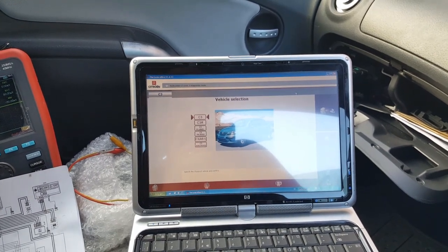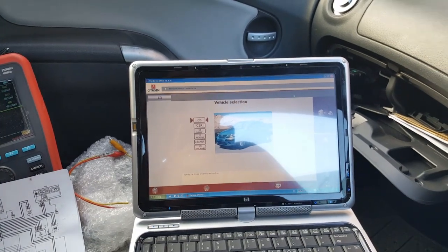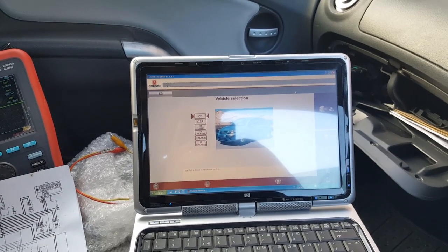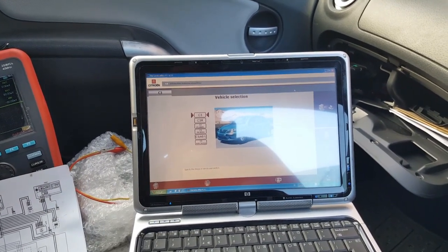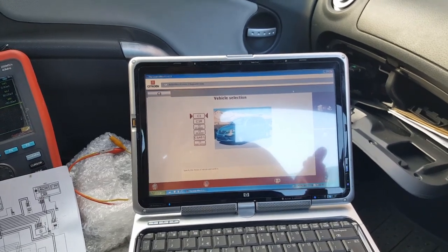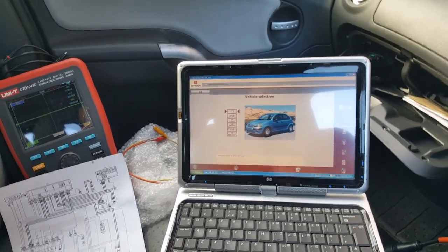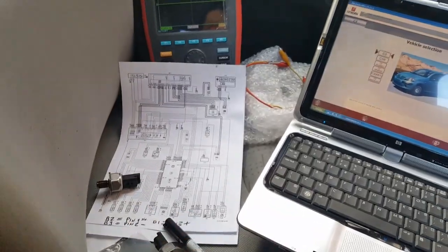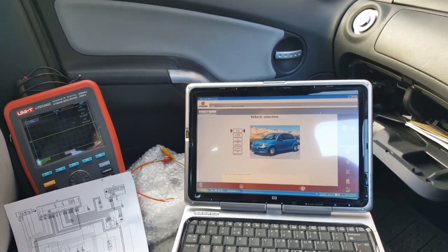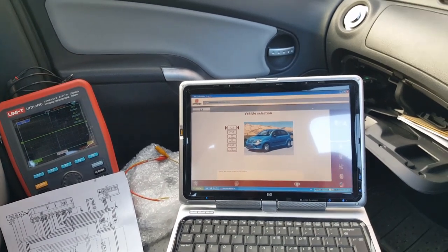When I checked the freeze frame, which tells me the status of the engine at the time of the fault, it showed 1700-something bars, which is obviously full pressure. When I measured the sensor exactly the same way as the original one, it was reading 5 volts, constantly. It wouldn't change. Ignition on, engine running, it would read 5 volts.